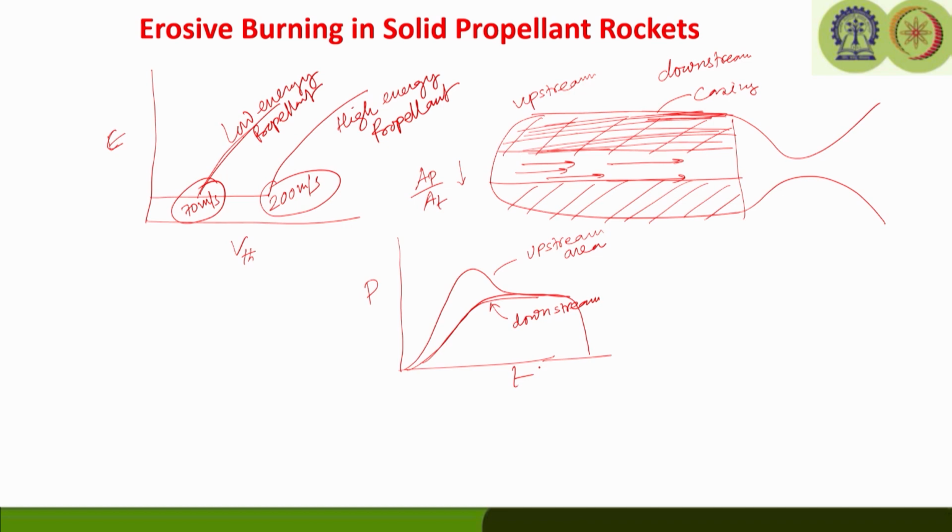From the flame front, radiation heat transfer and convection heat transfer take place. During ignition, hot particles impinge on the propellant surface, and the heat conducts into the propellant, causing pyrolysis and decomposition of the propellant, which creates further fuel and oxidizer species that burn there, creating the combustion products, and so on.